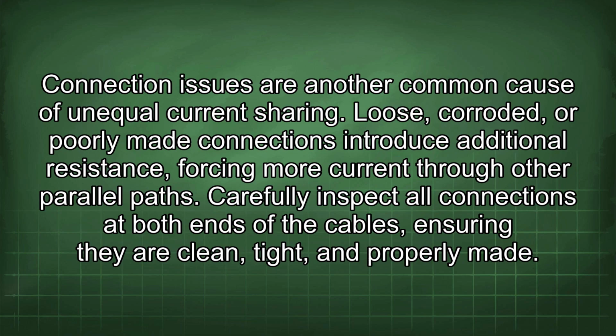Connection issues are another common cause of unequal current sharing. Loose, corroded, or poorly made connections introduce additional resistance, forcing more current through other parallel paths. Carefully inspect all connections at both ends of the cables, ensuring they are clean, tight, and properly made.